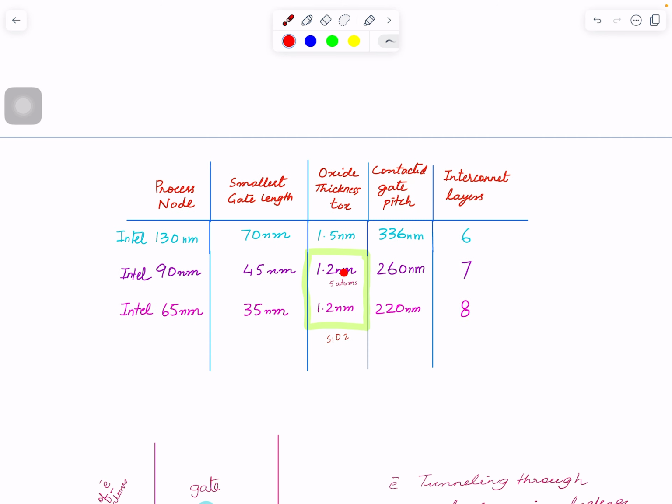90 nanometer, okay, boom, 70 nanometer down to 45. 65 nanometer, you see that? Slowed down. Here is the major factor that was causing that slowdown. You see, this was not changed. And that is really the thing that they addressed on 45 nanometer, which is the next one. But even on contacted gate pitch, overall density was reduced because you have to get that 0.7x type of shrink every process technology, and that was achieved.